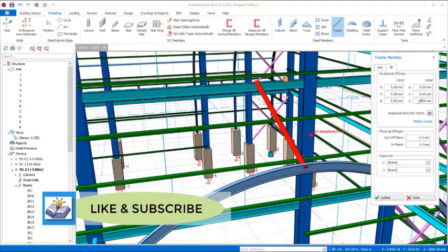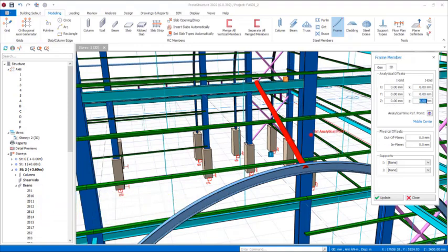So we are offsetting it in the Z direction. Let's go 50 first and see the extent. We have to prefix it with minus, just like this. Update. You can see it goes down a little bit, so let's make it 100. Okay, not 100, will be fine. All right, so we have it to be 100, just like this. Update. This is good. All right, that is in the J direction.